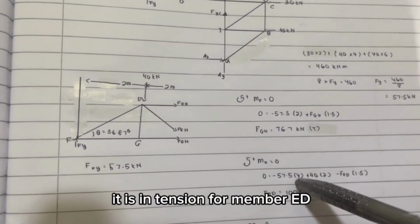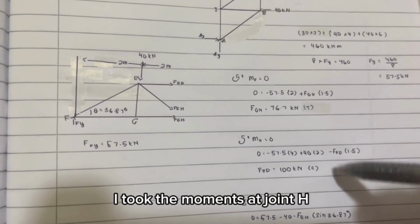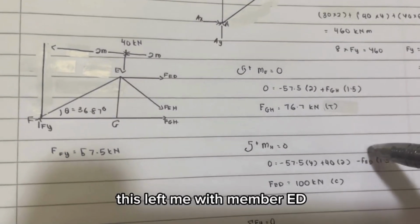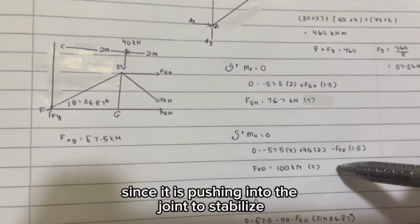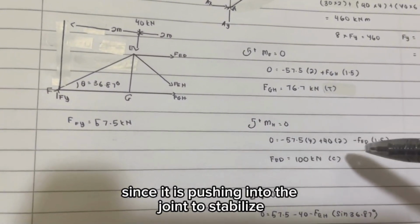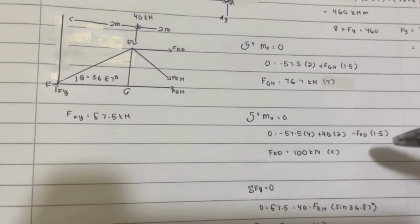For member ED, I took the moments at joint H. This left me with member ED. The result is 100 kilonewton. Since it is pushing into the joint to stabilize the load, it is in compression.